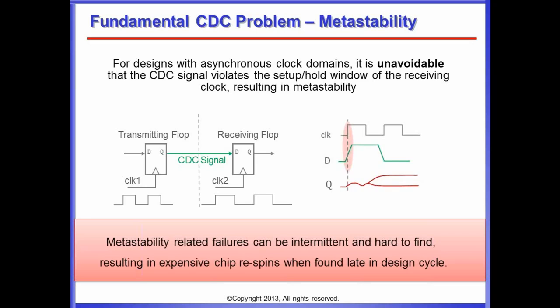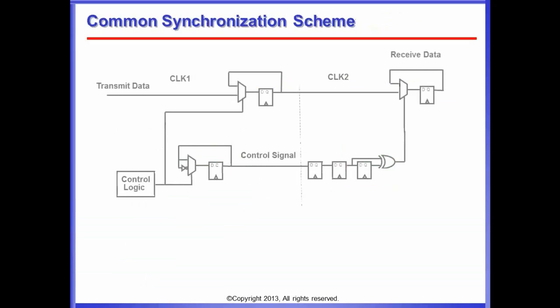This is not a problem for synchronous clock domain crossings, where you have well-defined and aligned edges, you know your timing and you can verify this with traditional STA. But for asynchronous clock domain crossings you need some kind of add-on or additional analysis. So in the previous case you could simply add another flip-flop after the first receiving flop to overcome the time until the flop settles.